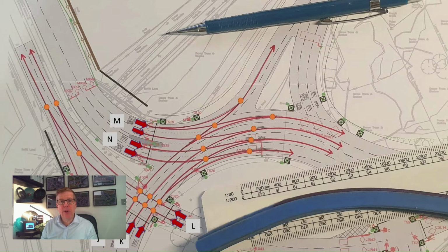The intergreen period is calculated by subtracting the distance for the phase gaining from the phase losing right-of-way, which gives what is referred to as the X distance. On approaches with multiple lanes, measure all the available transit paths and always use the longest distance to calculate the X distance.